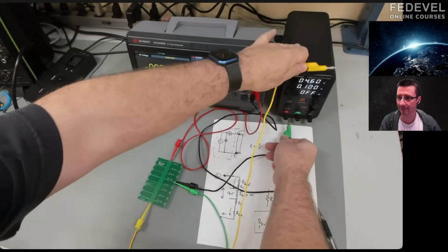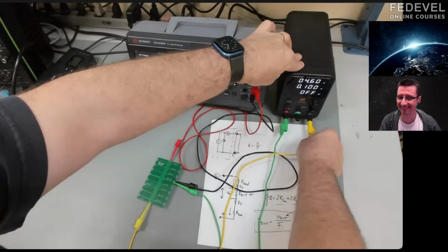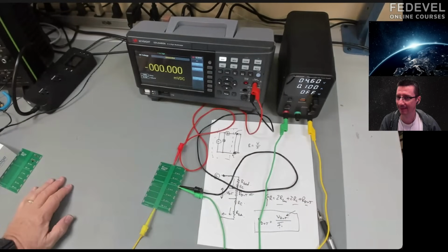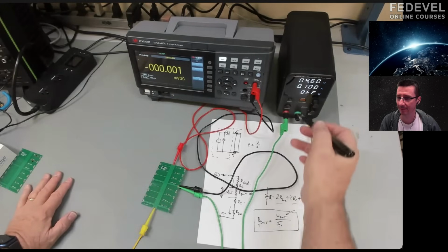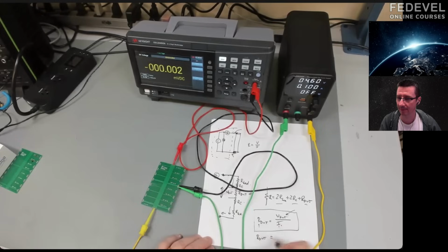So I'm going to set up my power source here, and I just want to make sure it's off, just to make sure I'm not going to blow something up. And now we're ready to turn it on. And I set it for 100 milliamps, 0.1 amp. I like doing it in nice multiples of ones and tens, because now the resistance of that wire is going to be whatever voltage I measure divided by 0.1 amp, which is that voltage measured in volts times 10.